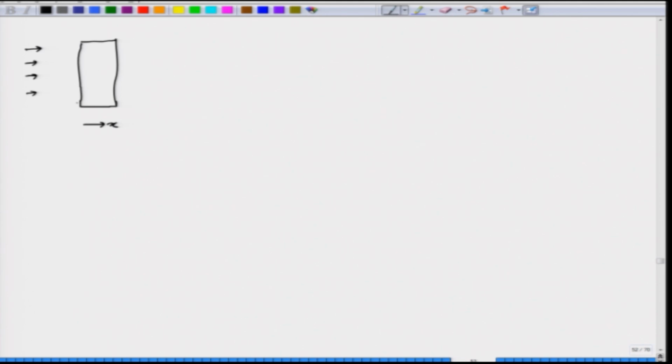At the surface we have x equal to 0, and the components usually have a large thickness, so that during the carburizing treatment the carbon does not penetrate all the way up to the other surface. So we can maintain the infinite boundary condition. In this case x varies from 0 to plus infinity. This is called a semi infinite slab boundary condition.